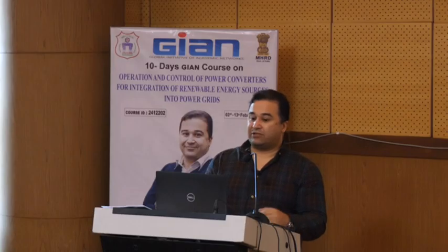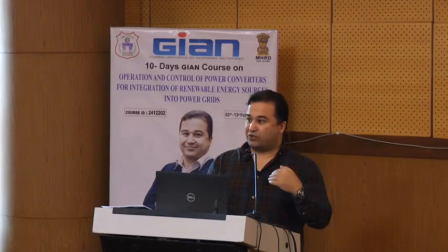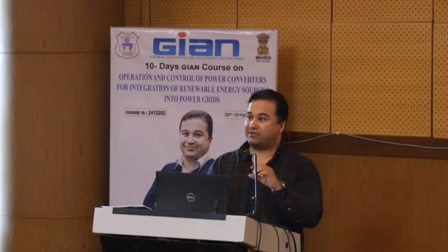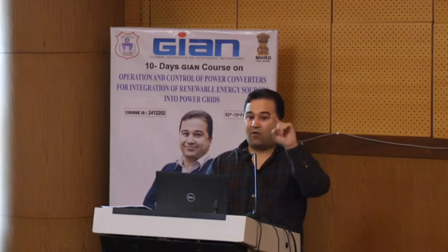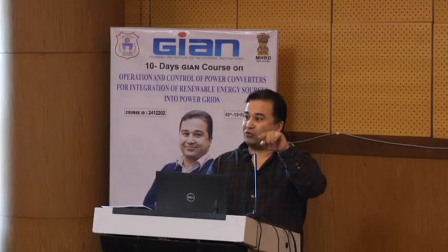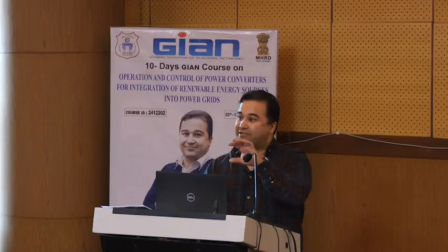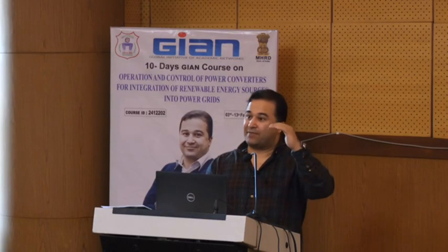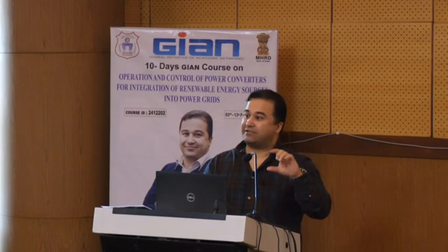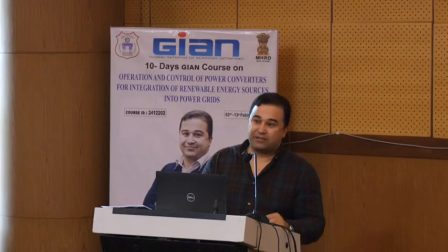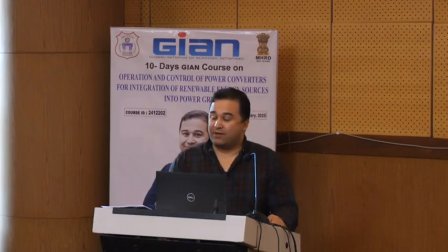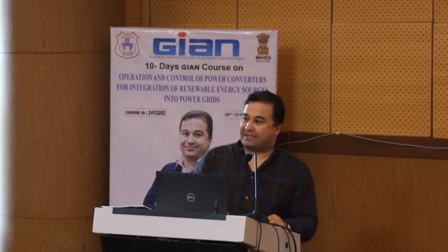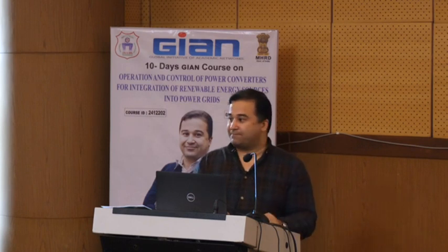So they decided to change the voltage control to current control. Instead of impedance, they use the admittance of the system, and this 1 over L di/dt plus R works like a filter. Instead of increasing the disturbance, it filters the disturbance. It's actually a very smart technology they used. But we will discuss the details of this technology later.